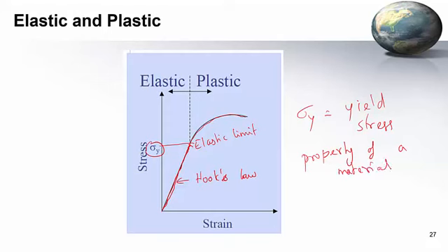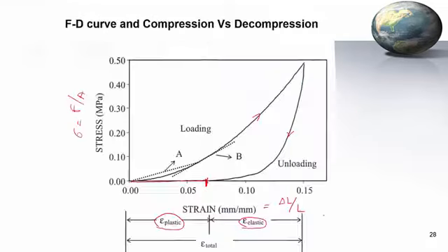So if you are designing a material that is going to undergo the load in a mechanical system, let's say to harvest, you want the stress to be below the yield stress because you don't want a permanent deformation. So if it is a bridge, when the truck goes by, there is going to be a little compression on the pillar, but you do want it to rebound back within the elastic limit so that when the next truck comes in, it presses it back and it rebounds back, and there is no permanent damage, and then it can last for a long time.